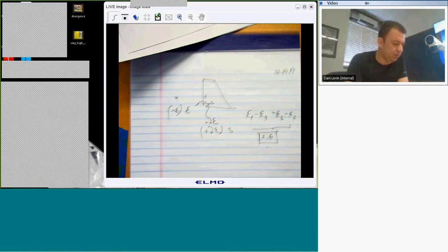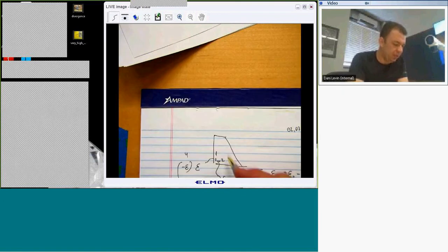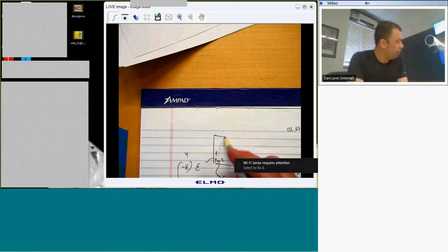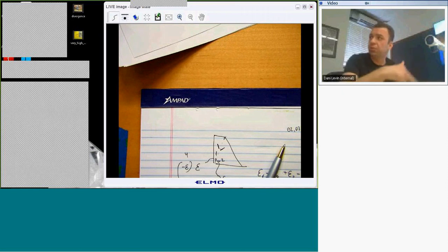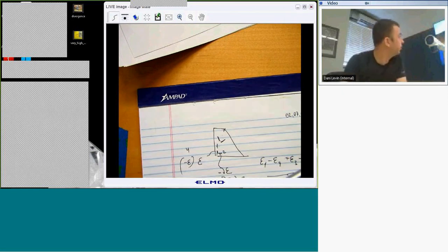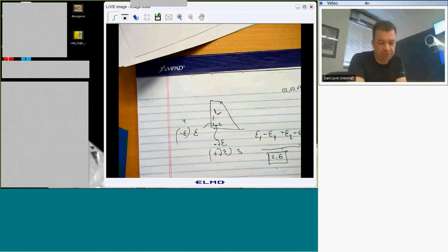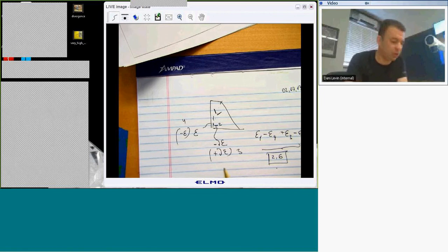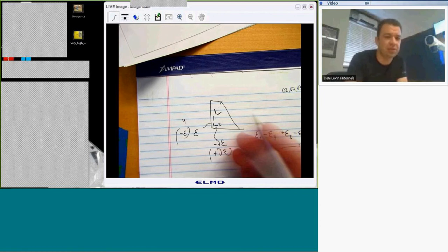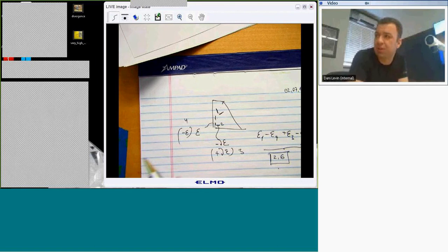And the other bridge is pretty much at 45 degrees around the nodal line, because if you twist the cylinder, the twisting stresses will go at 45 degrees. So this is standard. Actually, if you want to instrument your aircraft for flight test, this is the way you do it. If you want to measure the loads on the wings, on the structure, or in any place on your aircraft, this is the way you do it.